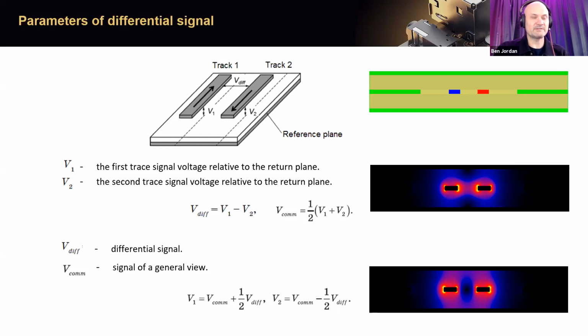So at the top, you can see I've created a board layer stack up as a bitmap where the light green color is ground planes, the red is the true, and the blue is the complement, and those are equidistant from the top and bottom ground planes. This is not broadside coupled, this is an edge coupled stripline differential pair, and the intensity of the electric field in differential mode is that image in the center to the right.